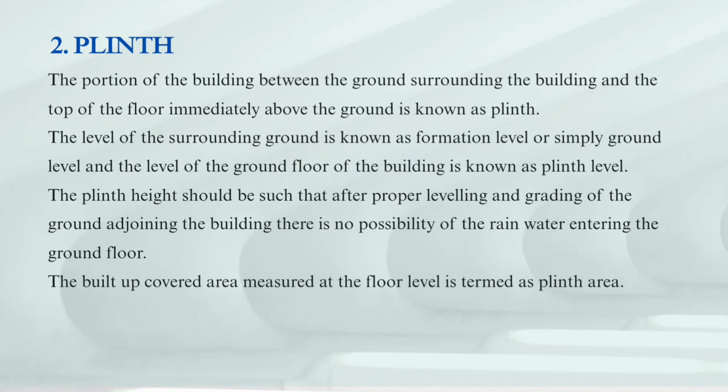The plinth height should be such that after proper leveling and grading of the ground adjoining the building, there is no possibility of the rainwater entering the ground floor. The built-up covered area measured at the floor level is termed as a plinth area.